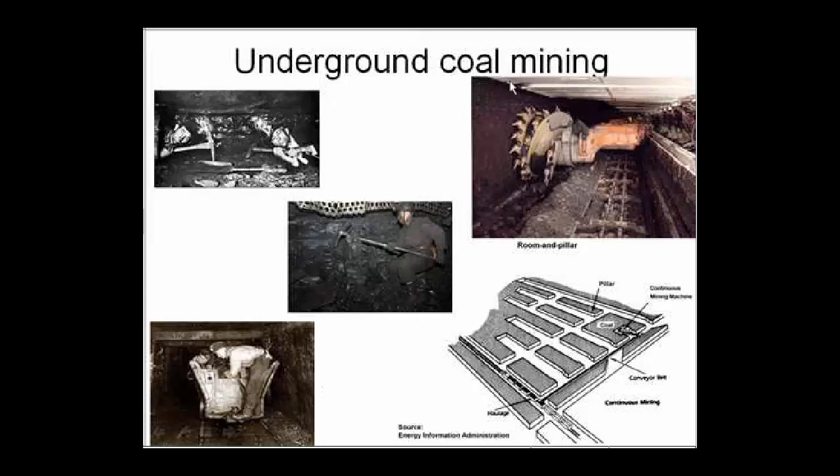More modern and more mechanized forms of operations are room and pillar, and forms of long wall mining. There's an example here where you'll find whole areas of large openings where machinery can run on rails and scoop and extract much larger quantities than individual miners can, or even groups of miners can. And the pillars are left to support the overlying rock, so the whole system in the above ground surface doesn't collapse or sink catastrophically, but then as much extraction occurs between the pillars as possible.